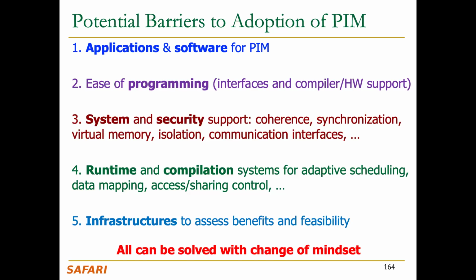You can do triple row activation only in that part of the array, and you move or copy the data using row clone, which we mentioned, from the other part of the storage into that part of the array. This solves multiple problems. And so even though you have to keep copying the data, it's still way cheaper than anything else.